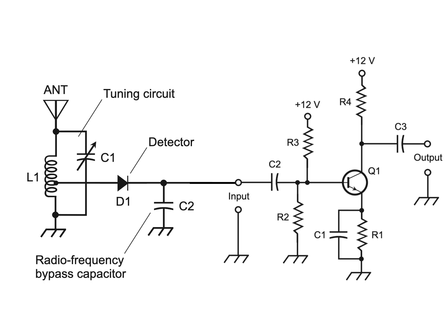Because this audio amplifier takes an extremely weak signal and boosts it to a reasonable, but not particularly powerful, level, it's sometimes called a preamplifier. If you want to drive a set of speakers so that the students in a classroom, or the audience in an auditorium, can hear the output from the crystal radio, you'll need more amplification. That extra audio boost can be provided by one or more additional circuits called power amplifiers connected to the output